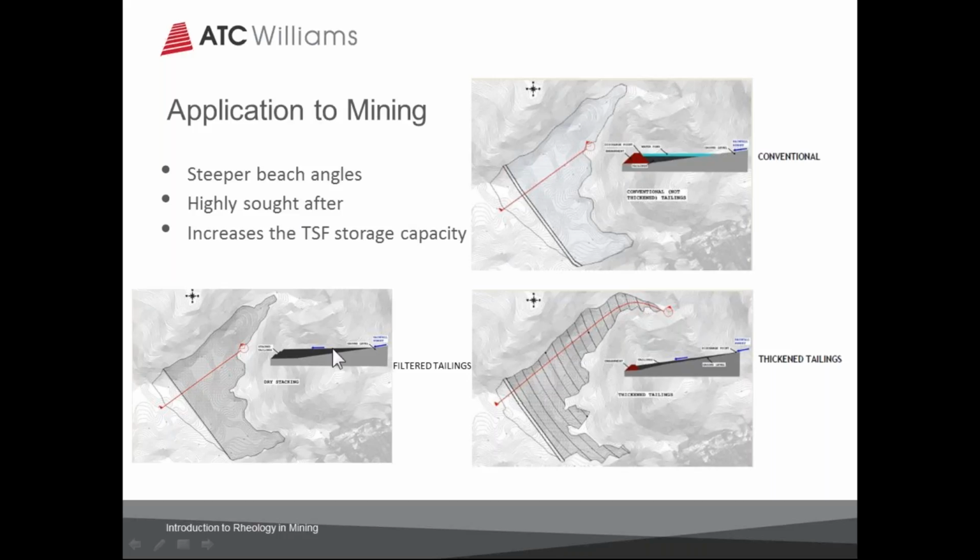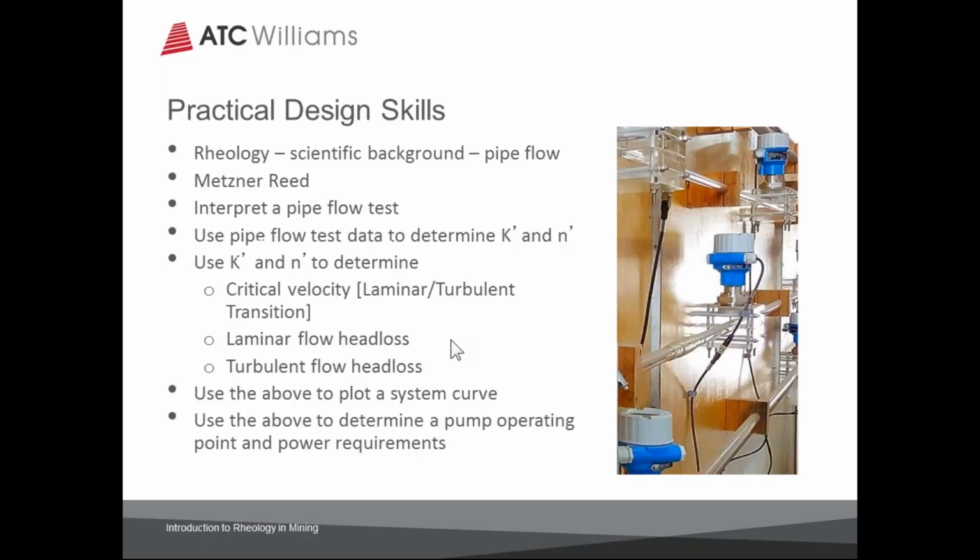And if we just go to the logical extreme, if we have filtered tailings, we can stack it up at its geotechnical limit like that to get the steepest slope. So if we can understand and manipulate the rheology to suit what we want, that would be a really important part of the tailings storage process. Looking at some of the practical issues now.